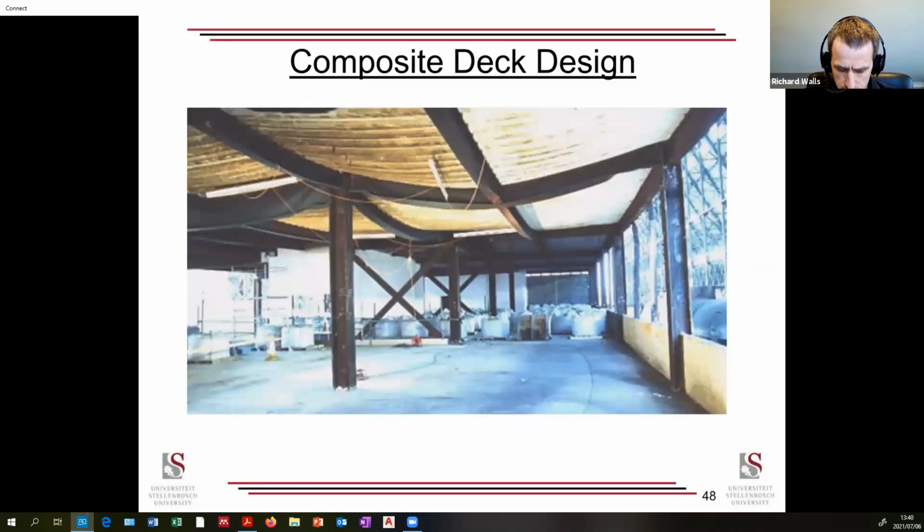Well, the gas temperature, the steel temperature, I can't remember off the top of my head. But the steelwork got very hot, deflected, sagged, but the whole thing holds together and you get what's called catenary action. You have rebar in that slab that is protected, and it allows you just to hang your slab off the structure around it. So your loads pushing down are carried by a hanging catenary of resistance, provided you can guarantee the capacity of your primary beams. Then who cares if this beam fails? Well, it's just part of catenary.